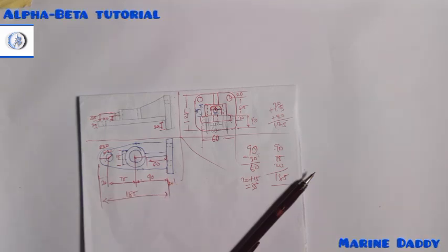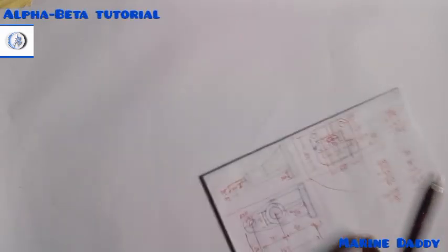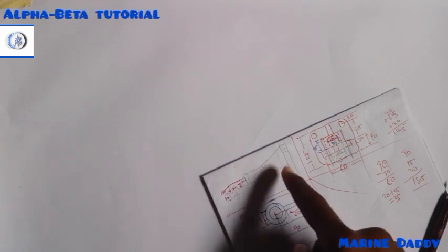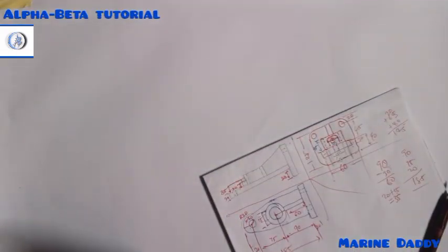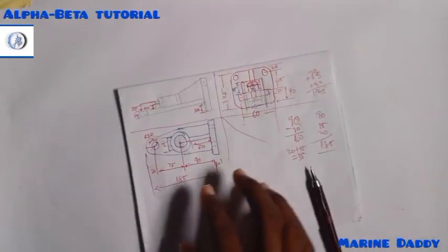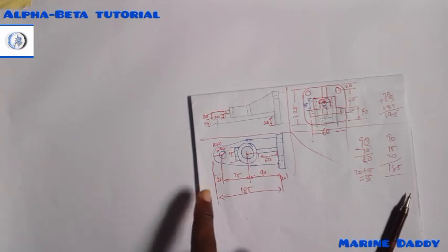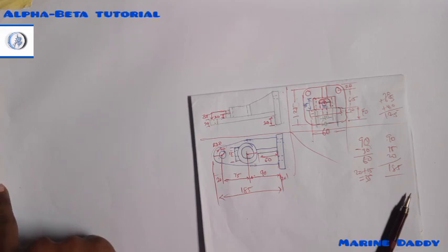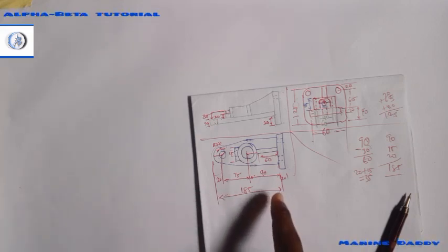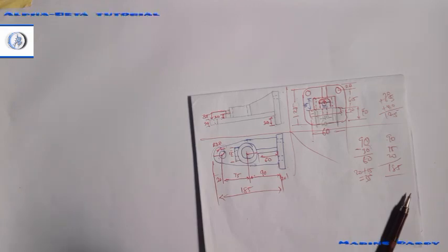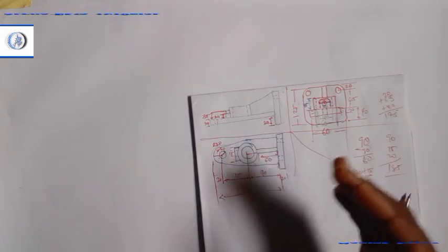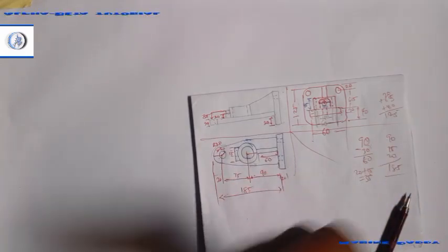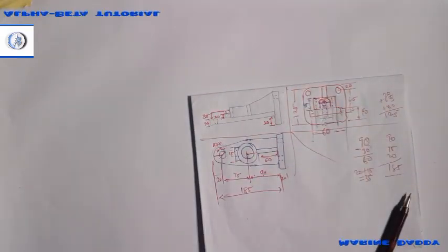So wherever I'm drawing, I must make sure that the length from this side to this side is greater than 205. So let's say I will work with 225 or 235. I like giving an extra 20 or 30 so that my dimensions can come in.